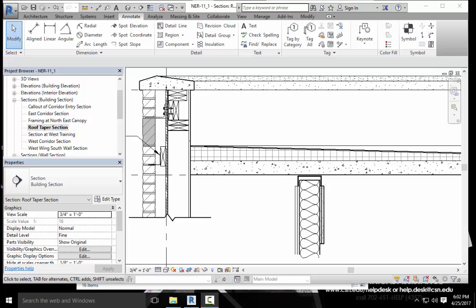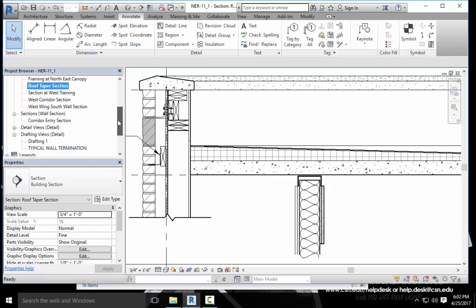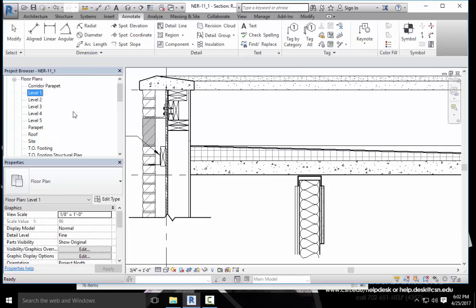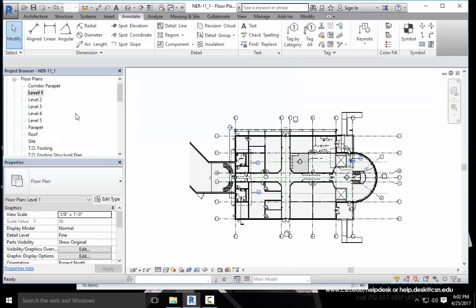Adding a section to another view. You already know how to add a section marker in Plan. What you may not know is how to tell Revit that you would rather specify the reference. In this procedure, you'll go to Level 1 Floor Plan and add a section pointing to your drafting view. In the project browser, open the Level 1 Floor Plan. Interesting, I think we have a typo there. Okay. Floor plans, level 1. Zoom in on the area of the east wing shown in figure 11.72.